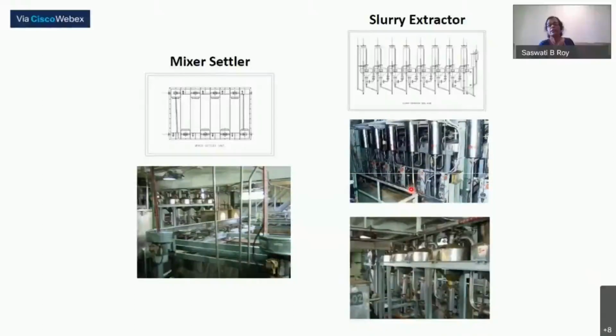In this mixer, the same way both the fluids are coming, like your solvent and the feed, and here mixing is by air. So compressed air is being used for mixing and lifting air, organic and aqueous will be at the top and bottom, and they will move countercurrently as in the case of mixer settlers. So you can see that here the hold-up volume is very high.